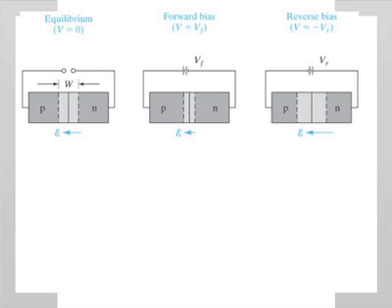On the other hand, when you have negative bias, the opposite happens. Okay? This is negative, that's positive. The applied field is in the same direction as the built-in field. So you're increasing that reverse field. Okay? So you can see the other implication is that if you look at the depletion region, as you apply a forward bias, the depletion region gets smaller. And we'll see why in a second. Okay? And you can imagine why, because you're reducing that built-in field, right? That total field has gone down. You can see it. It's smaller than that.